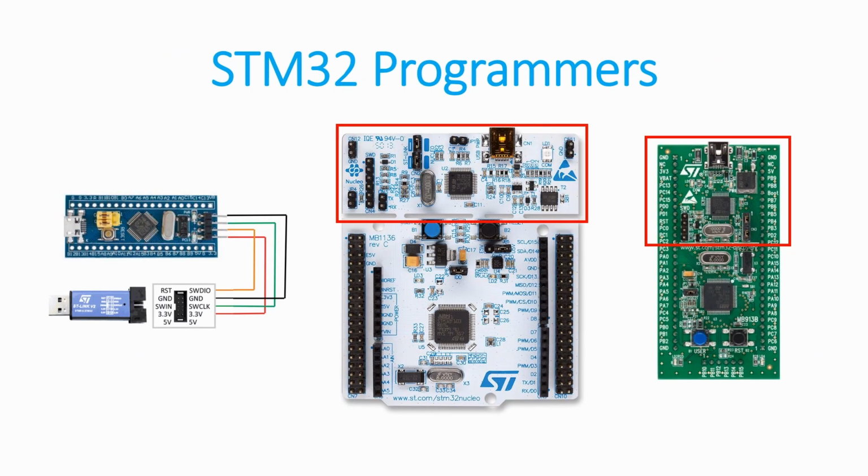So something to keep in mind about the STM32s is that to actually communicate and be programmed by a computer, you need a programmer. So boards like the Blue Pill will require an external ST-Link programmer. You can easily find, say, an ST-Link V2 on Amazon and use that. On the other hand, boards like the Discovery and the Nucleo have on-board programmers. The Nucleo, funny enough, actually designs the board in such a way that if you don't need the programmer anymore, you can snap the board in half and take off the part with the programmer.